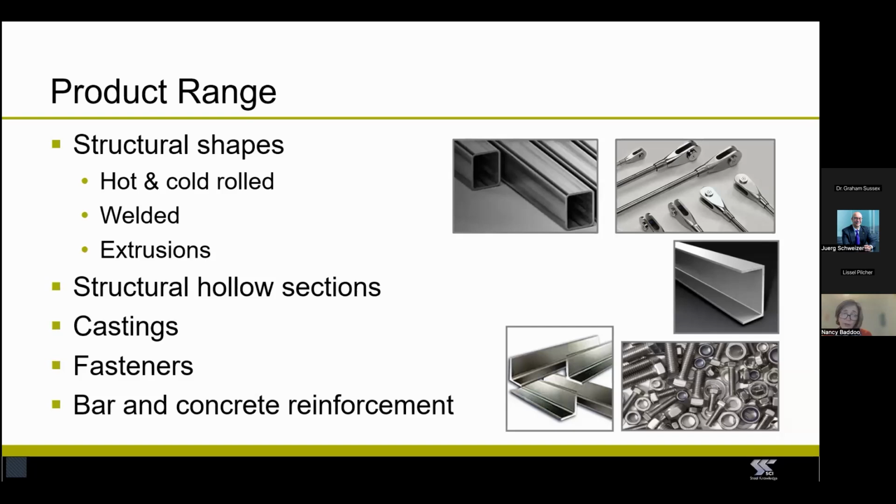Custom fabrications and short runs are readily available in duplexes. Bear in mind, for stainless steel, you're more likely to use fabricated, optimized, custom design sections. And it's worth it because the material is more expensive.